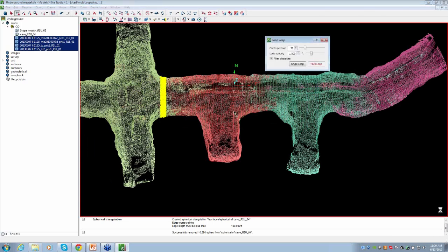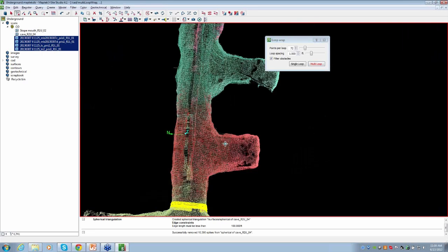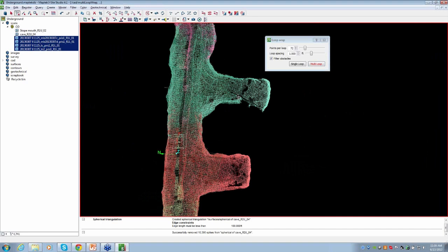All right. So as I mentioned, you will need to do another single loop when you change orientation. Let's see here. Perfect. So go ahead and select one right there, and we'll do a single loop. And then I'm going to make sure that I go over the area that we did with the other drift going in the opposite direction. And I'll do the same thing down here, starting at the end, creating a single, and then making sure I get some overlapping data there.